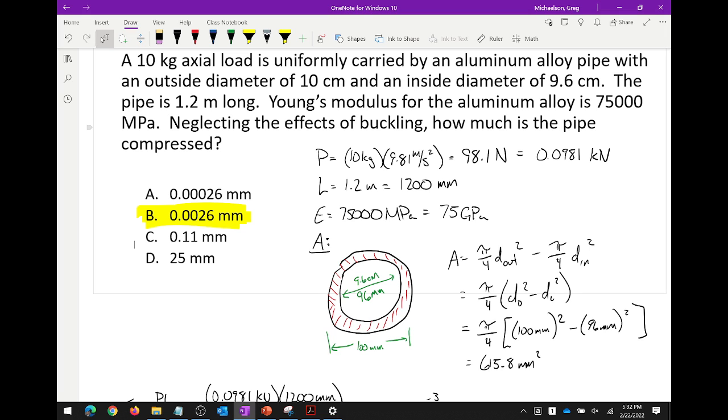Yeah, no, that's a very good question. So in the reference manual for the last problem, for the moment of inertia of the triangle, that's actually given as I, XC. Mm-hmm. And any time that you are trying to determine bending stresses, all of the bending stress formulas, sigma equals My over I, the y is measured from the centroid. You see what I mean? Because the bending theory has to reference the centroid, right? Because if you have a bridge beam supporting load, the beam doesn't care where the axis is. Do you know what I mean?